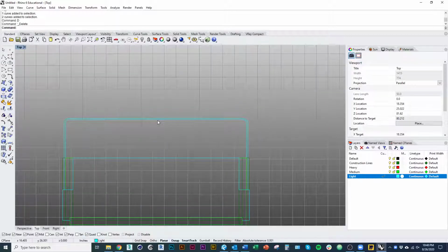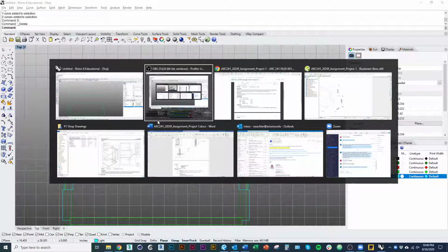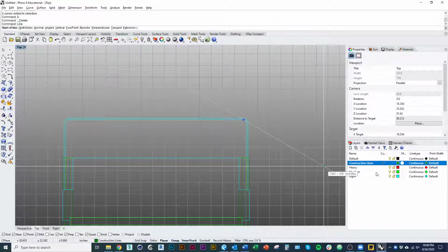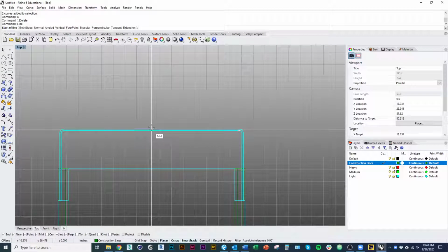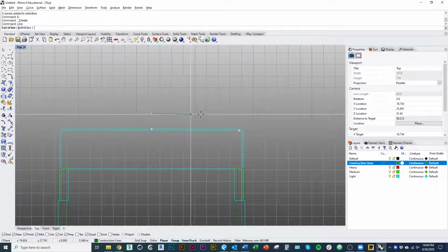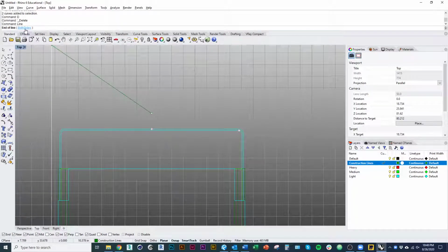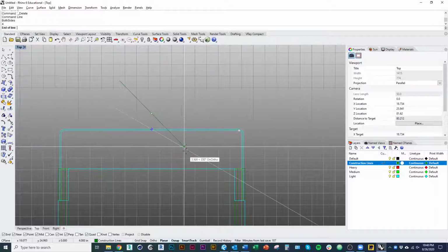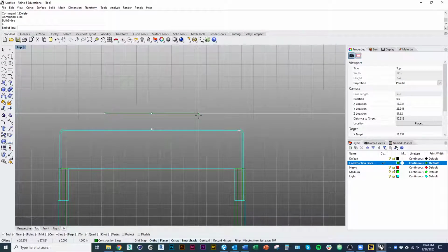The first thing we'll need to do is figure out where that spiral starts and ends, and it's 8 inches long and it's centered on the handle. So if I type in the command line, and again this is the instruction line, I'll go from the midpoint. I'm going to click this option, both sides, so I can draw out from the center. And if I want it to be 8 inches long in total, I'm going to type in 4. Press enter. So it'll draw 4 inches on both sides, which will be 8.